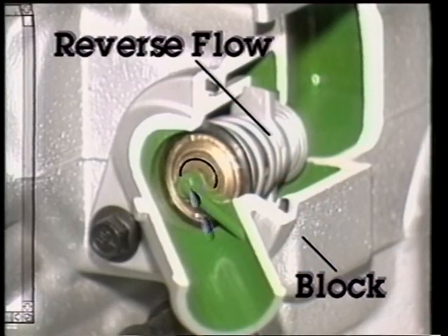Mentioned briefly, with a reverse flow cooling system, the water pump forces coolant through the head first, because the cylinder head surface temperatures can be higher than in the block.